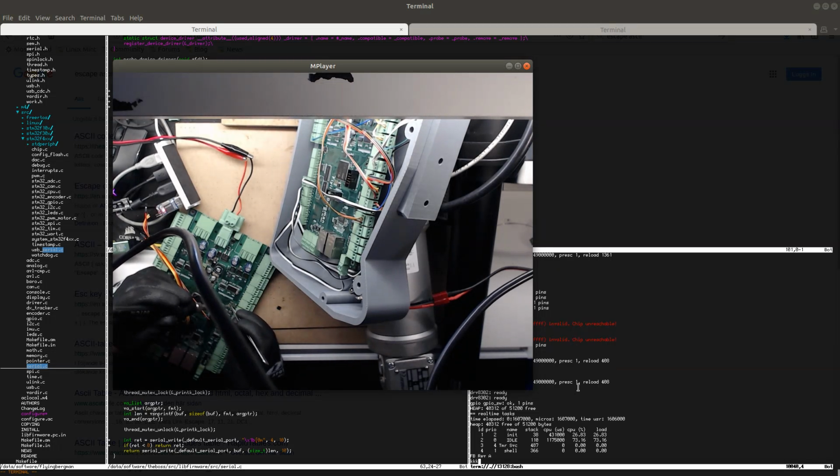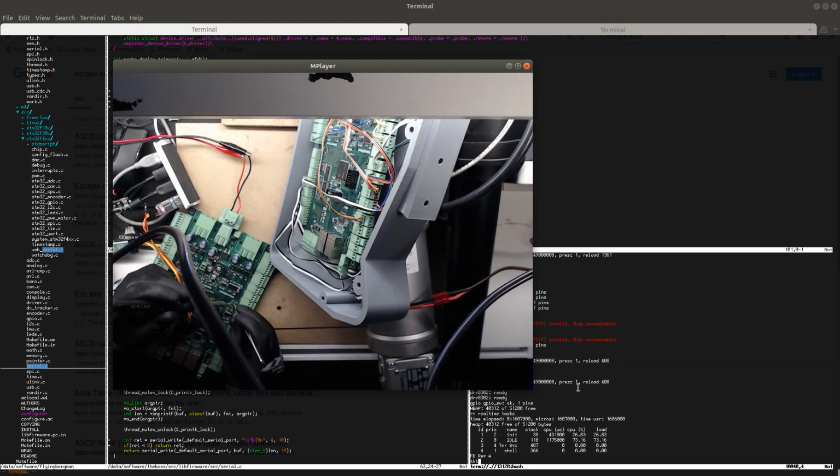Now the datasheet says that it doesn't really matter, that EP is just for leading away the heat, but I think it does matter. When I scratched the solder mask from the ground pads of the other two chips on the other board, they started working. So there's something about this ground pad that does require that it connects to ground.